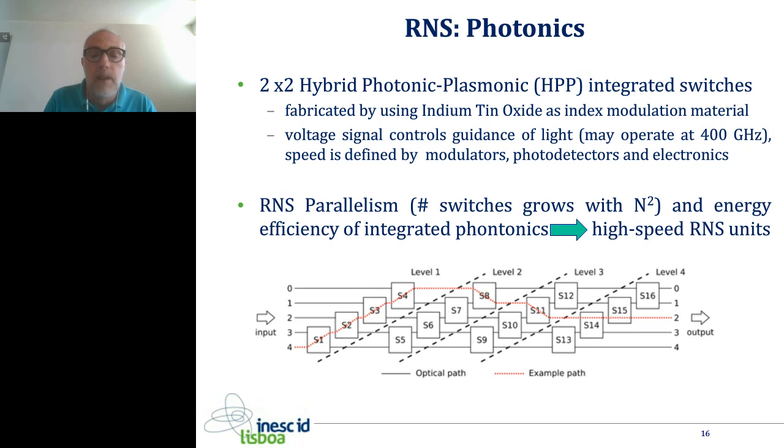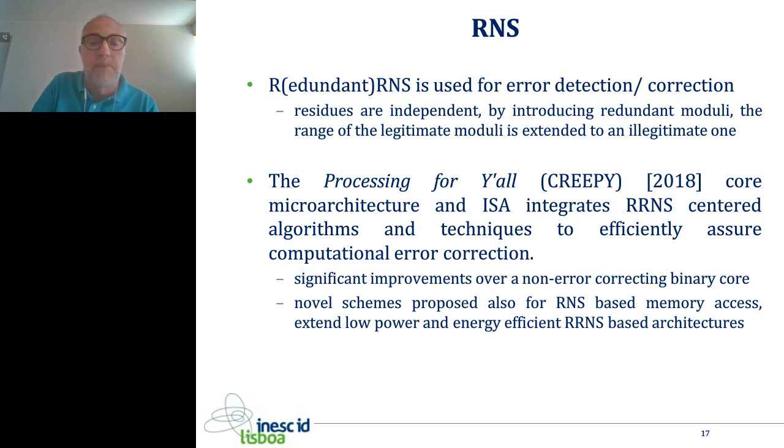So you are adding 4 plus 3, which modulo 5 is 2. So we go up at level 1, then we go down at level 2, down again in the switch of level 3, and then it's straightforward. This is represented by the number 3 that controls the behavior of the switch in each one of the levels. We apply it to integrated photonics, and residue number systems are quite important because otherwise it's difficult to implement arithmetic units in practice in this type of technology.